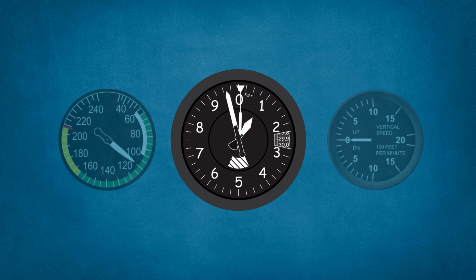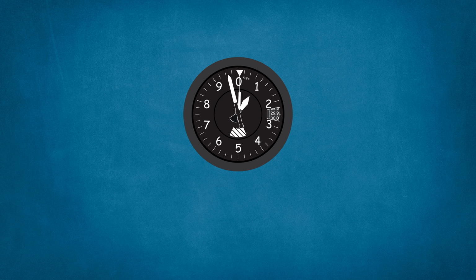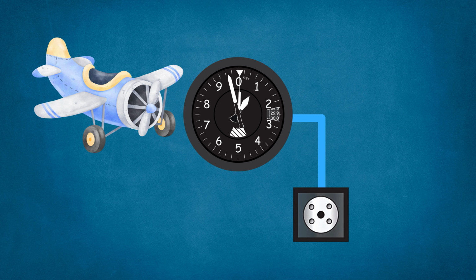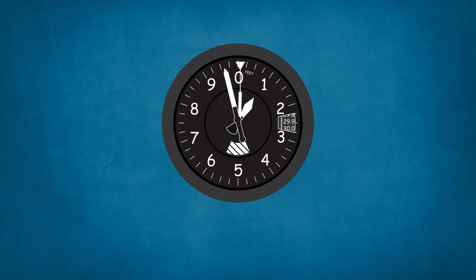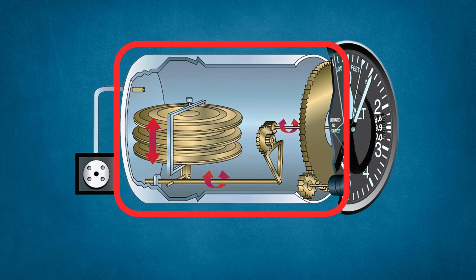The second one is the altimeter. The atmospheric or static pressure varies with altitude and weather. The altimeter uses the input from the static port to determine the altitude. The altimeter is the only instrument in small aircraft that gives the pilot altitude information. The altimeter measures altitude by comparing static pressure in its sealed chamber to a fixed pressure inside a diaphragm, set at 1,013 hectopascals, or 29.92 inches of mercury in standard atmosphere conditions.